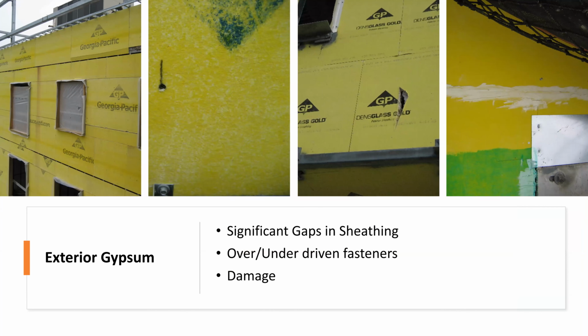So in this case, some of the same things, right? We can have significant gaps in the sheathing, right? If we're using self-adhered, spray applied or whatever, we have to do some pre-treatment to that. That pre-treatment could be a sealant, it could be some backer rod and caulking, it could be some sheet metal. There's a number of different strategies that can be used, and it's going to depend a little bit on the size of that gap and the air barrier going over top of it.